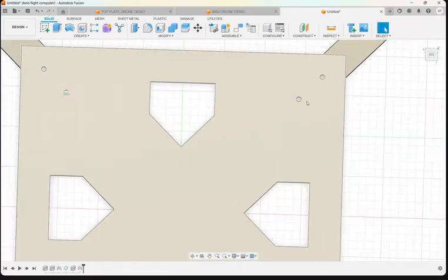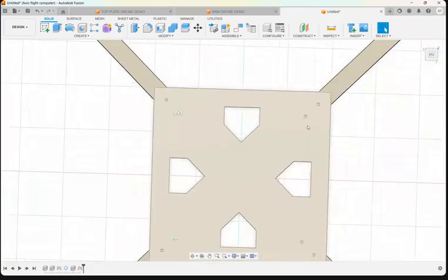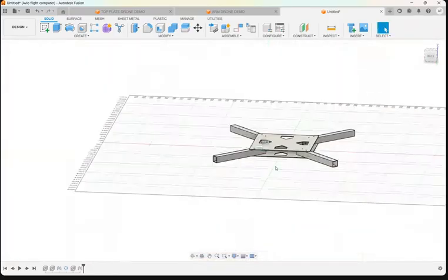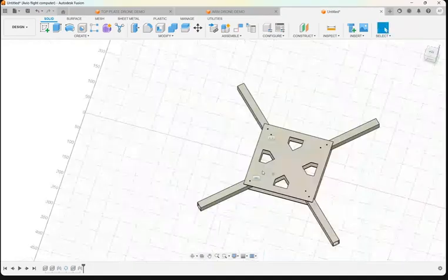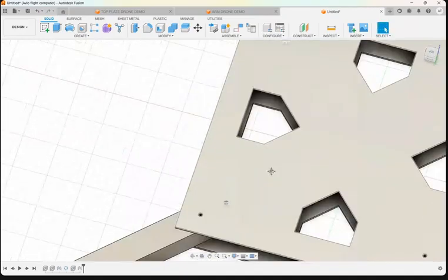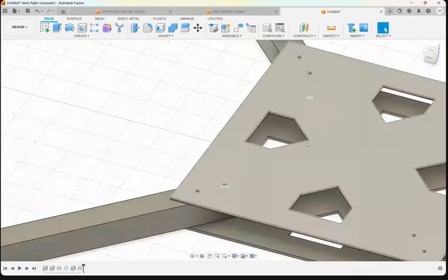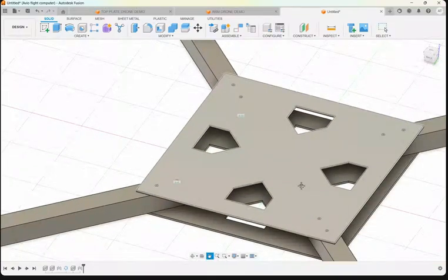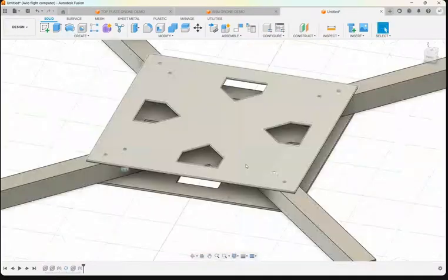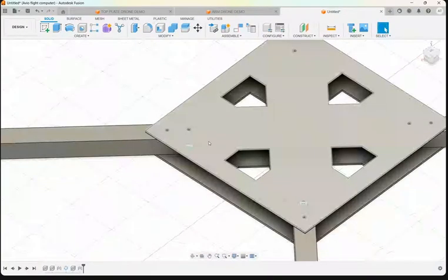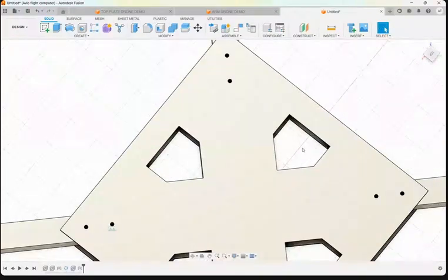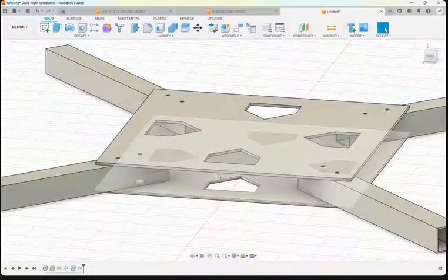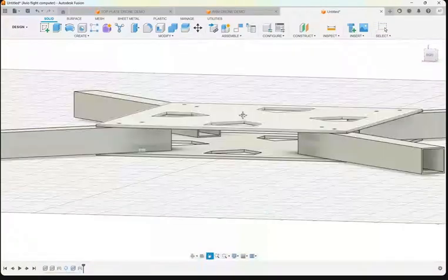Now you can see we have a through and through hole of 3 mm, particularly top plate and bottom plate. This is how you can start designing at a particular point, and I have even given some slots over here with these different looking shapes, so that my plate is not that heavy, and wherever stress will come on the plate, at least there it is holding, because screws will be there. So over here there is an item, and where we have nothing, the empty area, we can give some slots and can save some weight.